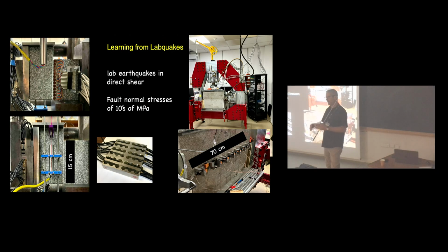I want to show you some aspects of different kinds of laboratory experiments. I'm going to draw a few examples from big data sets associated with laboratory shear experiments. And I'm going to take them from different cases. This is a buried granite, it's not Westerly granite, sample that's at Penn State University, with a series of strain gauges along a fault. This is a single direct shear configuration. There's a hypothetically frictionless bearing on one side of it. And you can shear this thing. You're measuring with a displacement transducer to see exactly what happens with it. That's the scale of it.